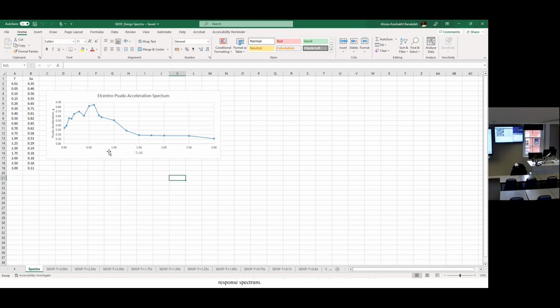Whatever mass you have in your structure, grab your total mass, put it on a scale to see how much your structure weighs, and multiply the mass of your structure by this number, and you will get your design force. Design your structure for that force, and you will be safe.